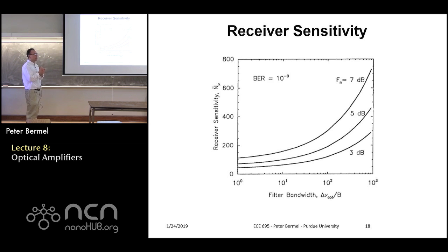Okay, so now I should introduce the concept of bit error rate before I try to explain anything else. Bit error rate is essentially saying, when you have a stream of zeros and ones, how often do you flip a bit at the receiver and receive a 0 when you should be getting a 1, or vice versa? So that's basically what that's saying. Usually the standard for telecom is that you want really, really low bit error rates, not surprisingly.